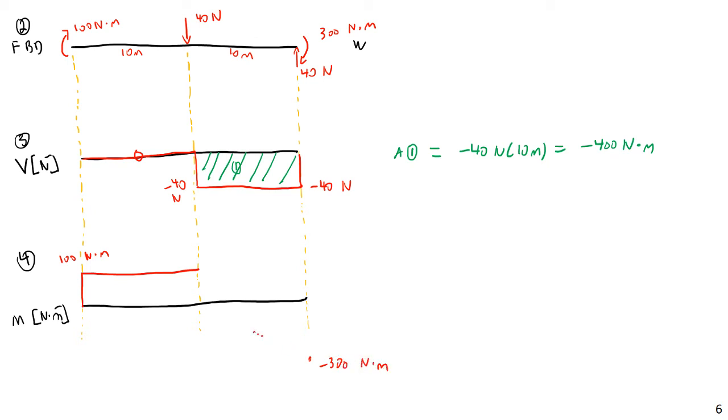And then we can ask ourselves, okay, well, what form is that equation going to take? Well, I know the integral of a constant value function like this is going to be a linear function, so that means we are going to drop down as a linear function. And if we wanted to, we could solve for that point just by using any number of methods. If we were concerned with where the moment was equal to 0, we could solve for that x point, and that actually would be useful, especially when we get to deflection. We'll see that later in a week or two.